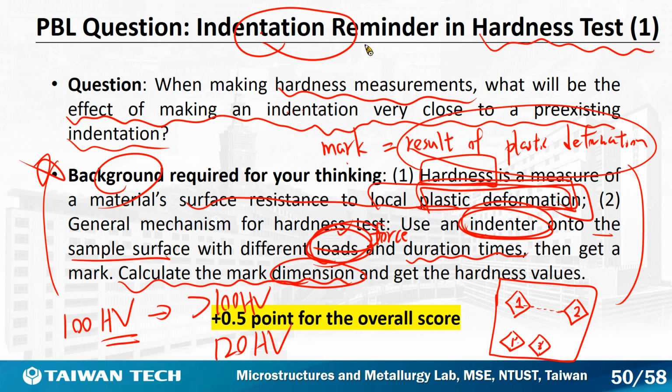So this is a reminder that when you are doing hardness measurement, you cannot put the indenter very close to the pre-existing one, because the value you get will not be the exact value as it should be. Okay, so this is a very important reminder. Otherwise, you will get the wrong data.